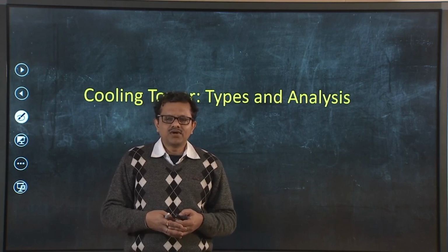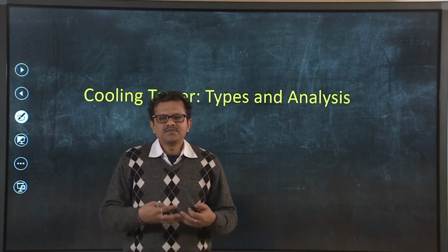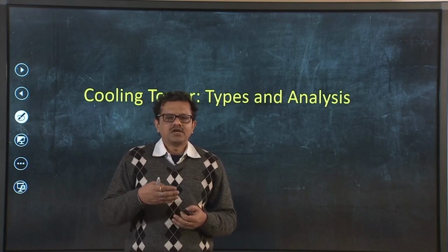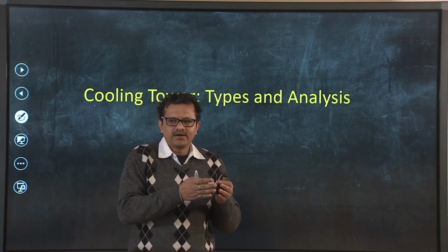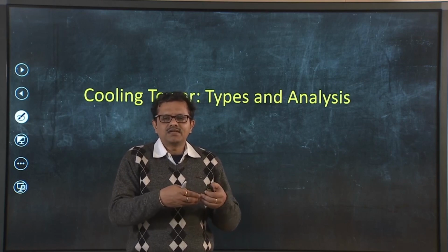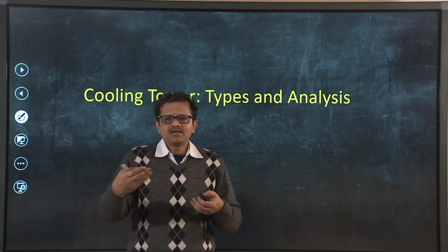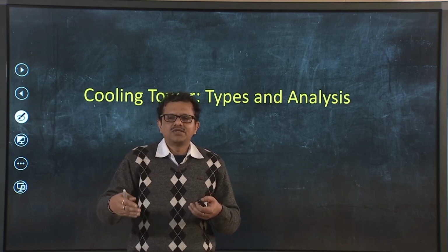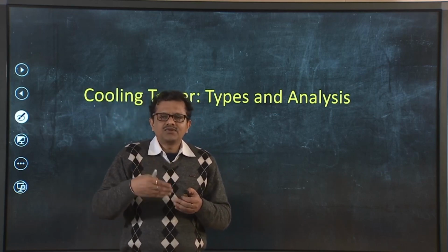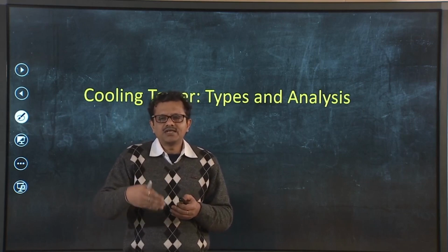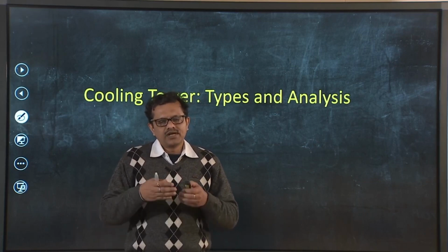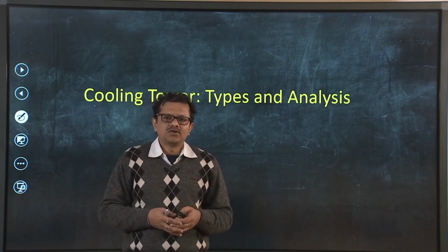So, even if water is available in plenty, because of these environmental factors we need to think about recycling the coolant, so that in the condenser it takes some heat from the flowing steam. Upon receiving heat, the temperature of the coolant will increase. In another circuit, that coolant will again release heat to another stream, and the device in which the hot water releases heat to another stream is known as a cooling tower.